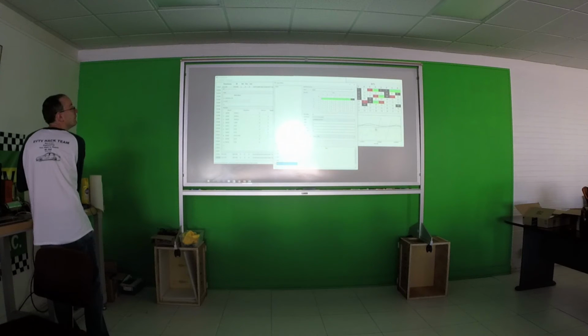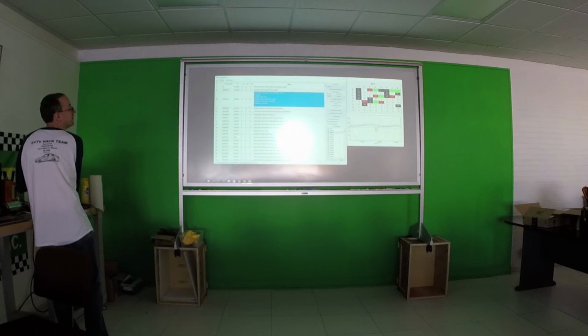That lets us turn those numeric values into text values. Personally, if I see that the gear is reverse instead of 3, that's a lot easier to interpret. So I'll go back here. With the data loaded, if I say interpret frames here, now all that stuff that I had in the DBC file, if I click that, you see that was inverter message 1. The motor RPMs at the time were 6162. The torque was only 0.6 Newton meters, and the throttle was at 15.288%. That is a lot easier than seeing 06, 80, 06, 00, 12, 18, 27.